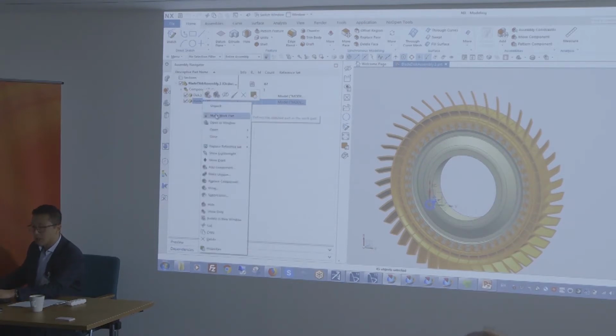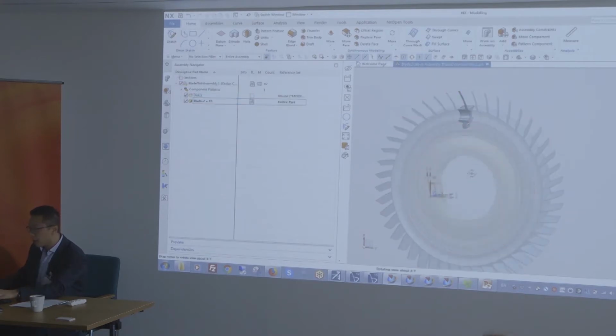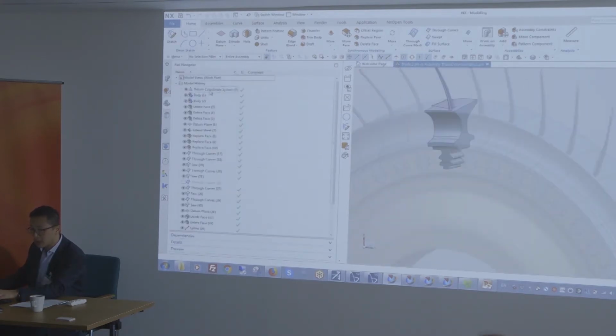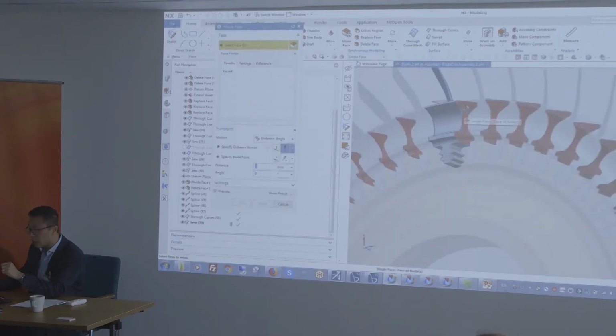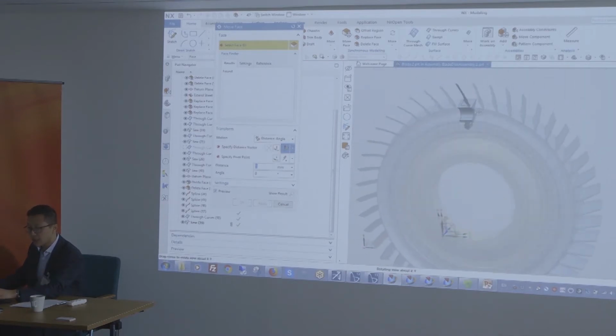Now what's kind of different here is that the CAD is embedded. So unlike tools like ANSYS SpaceClaim or SolidWorks, working either at the assembly level or at the part level, in this case, all of our CAD capabilities are available. So I could go here, look at one of my blades, and I could look at the history tree and see all of the different features that were used to create that geometry. I could add some of them, so I could create a command where I pull up the face, and you'll see it will modify the face or increase the thickness of it for all of the different components at the same time. So you can work, as we call that, in context of the assembly.